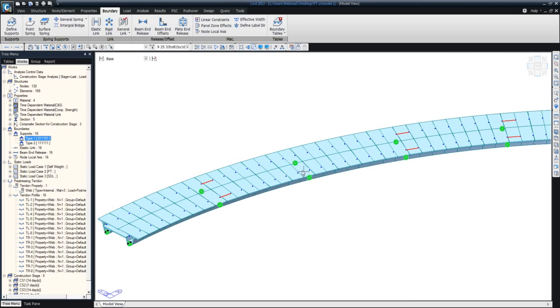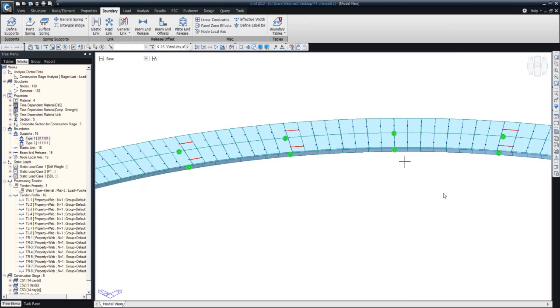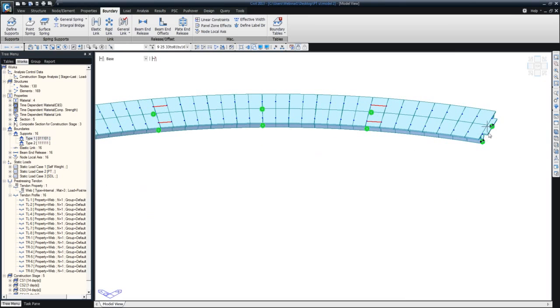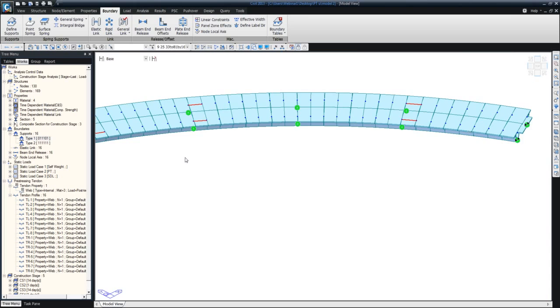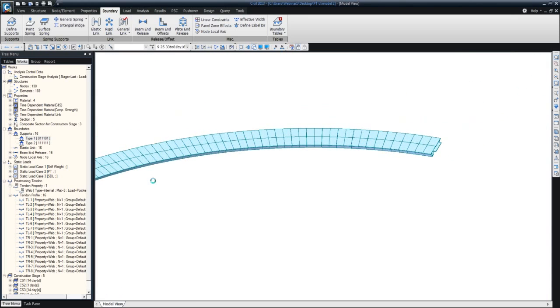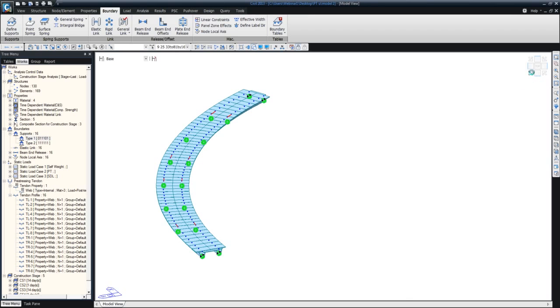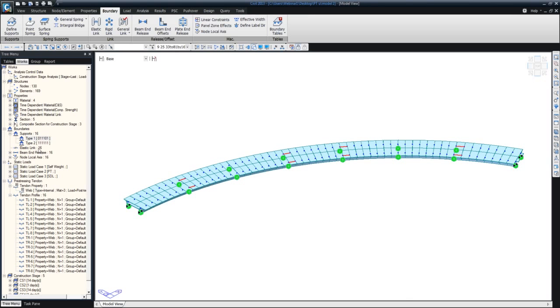So these are the locations, as you can see, where the beam ends are applied, are the shoring locations where you will be applying your temporary supports. And these are the expansion bearings at the other ends, at the two abutments. And the interior piers are fixed. Like this. And so let me unhide this and quickly walk you through the construction sequence.